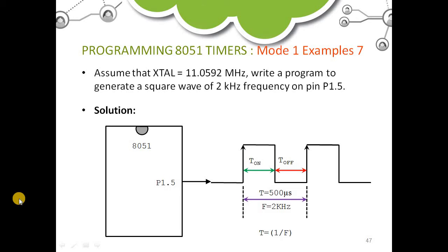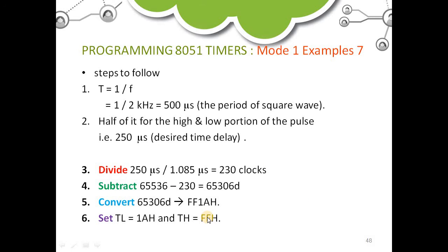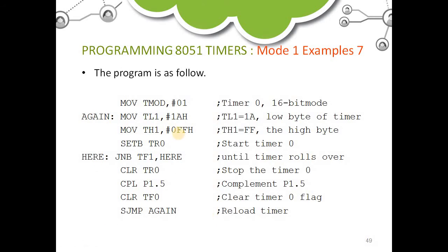So in the coding part, there was a change to make there. I have informed in that video also to make it 0. Set with TR0, clear TR0 and clear TF0, which was 1. Because we are using timer 0, this has to be 0. This 1 change is to be made. I have explained in the previous video session itself, still to notify that once again.